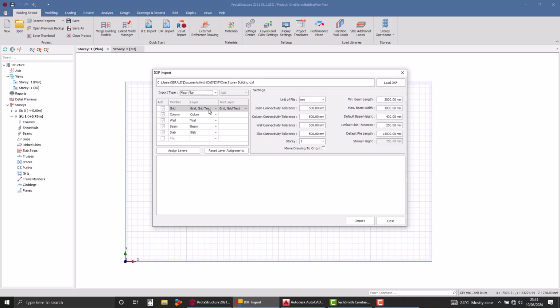In the absence of other layers in the reference drawing, axis and column layers can serve as basic starting points to designing a model. In this case, we are going to work with grid, text, column, beam, and slab layers, assigning them to corresponding structural members. Now, the grid layer will be assigned to the matching element of the model in view. I will do the same for columns.